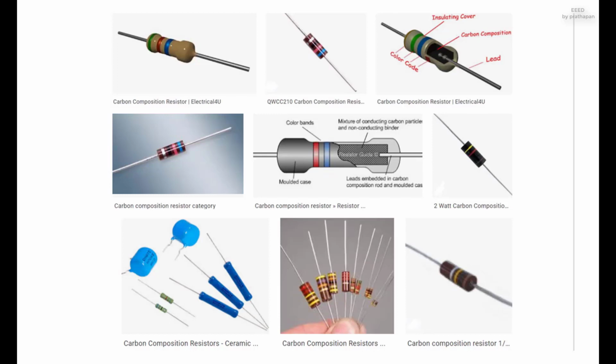These resistors are non-inductive, which provides benefits when used in voltage pulse reduction and surge protection applications. Carbon composition resistors have higher capability to withstand overload relative to the component's size. Carbon composition resistors are still available, but relatively expensive. Values ranged from fractions of an ohm to 22 megohms. Due to their high price, these resistors are no longer used in most applications. However, they are used in power supplies and welding controls. They are also in demand for repair of vintage electronic equipment where authenticity is a factor.